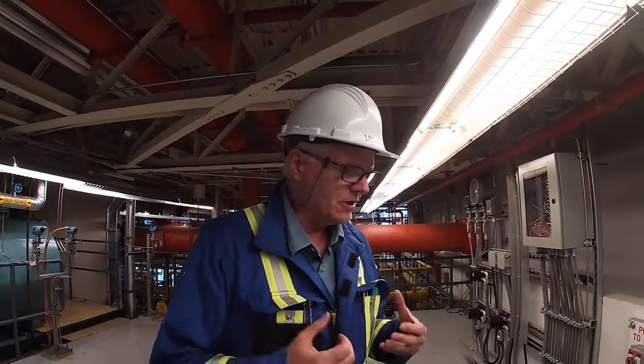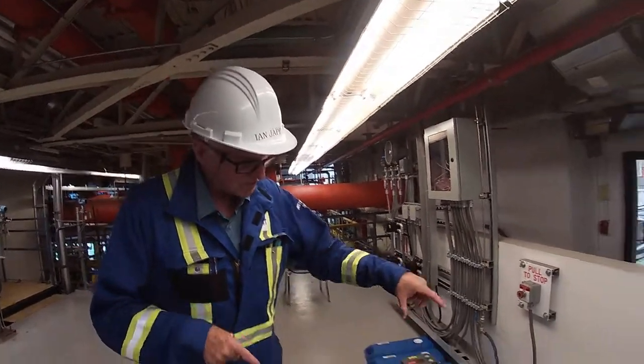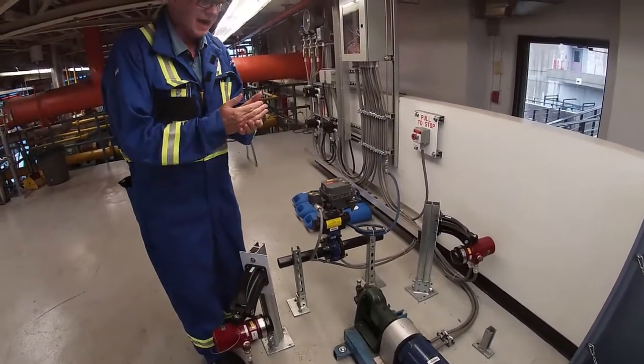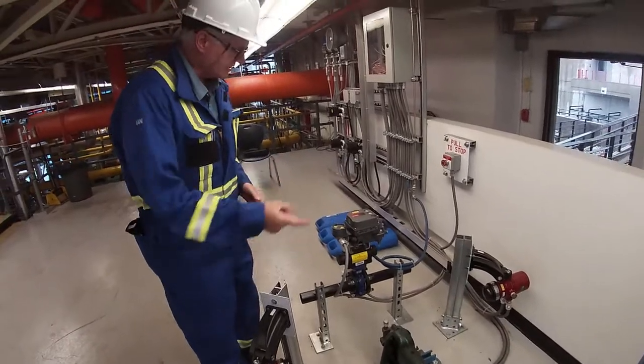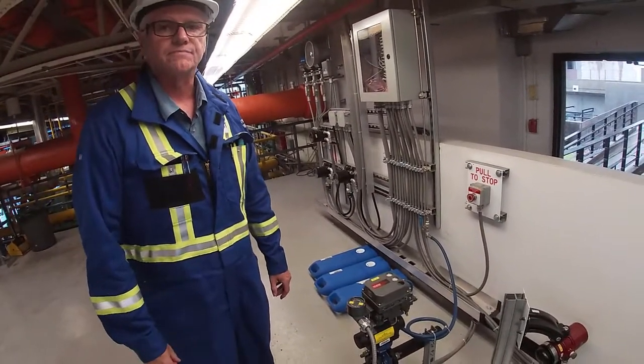And we wouldn't want to shut down our equipment on false alarms. So what we do is we have a voting system. If both of the fire detectors, the IR detectors, pick up a flame, bang, it'll shut down the pump, and it'll also close our fire isolation valve.